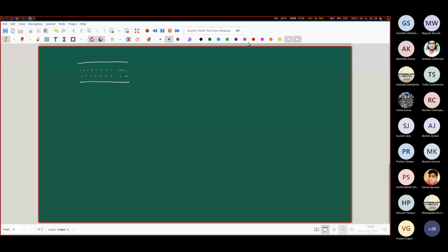And in this kind of situation, it is much more natural, instead of talking about the Cartesian XYZ coordinate system, to consider this Z, this R, and of course you understand that this is theta, that R theta Z coordinate system. So for pressure vessels, it is much more natural to consider this R theta Z or cylindrical coordinate system.